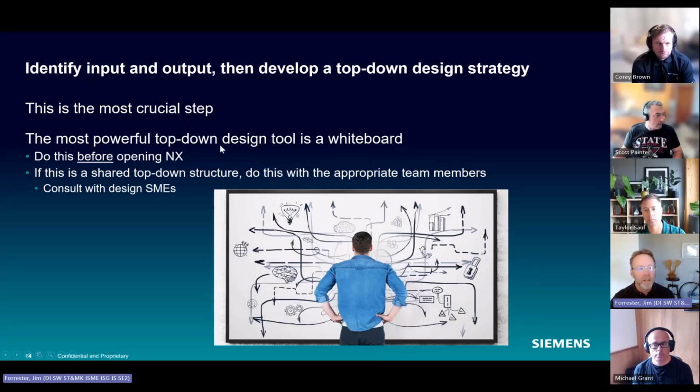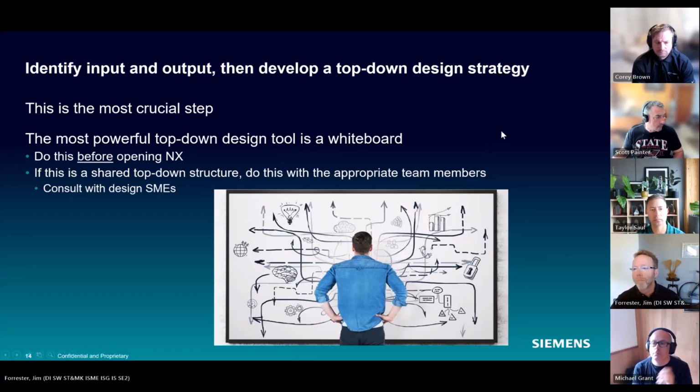The most powerful top-down design tool is a whiteboard. Do all of this before touching NX. If you have this in mind and open up NX first, it's a risky thing to do. Plan this out first. Use a whiteboard. Consult with design SMEs. Consult with the team. Especially if this is a shared top-down design structure. Some top-down design structures, only one or two people are going to use. If many people are going to use it, you've got to get everybody on board. They need to know the plan.